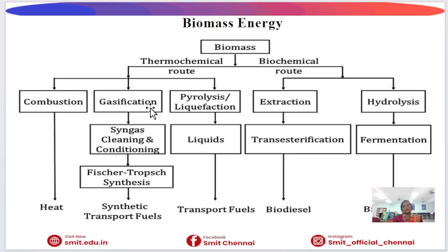It first goes through syngas cleaning and conditioning to remove the dust, tar, and impurities. After cleaning, the syngas enters Fischer-Tropsch synthesis. In this process, syngas is converted into synthetic transport fuels like synthetic diesel and petrol. So gasification finally gives synthetic transport fuels.